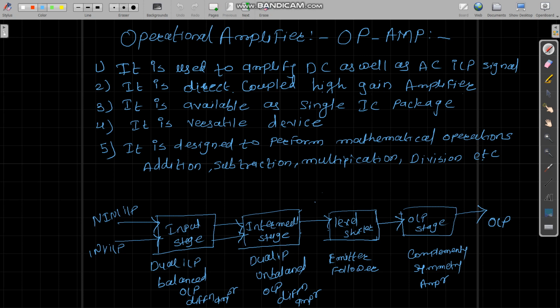As you can see, it is a dual input, which means both the transistors of the differential amplifier get input from this circuit. As it is unbalanced output, the output is taken only from one of the collector terminals, with respect to ground, and therefore only one output is shown here, and that output is given as an input to the level shifter.